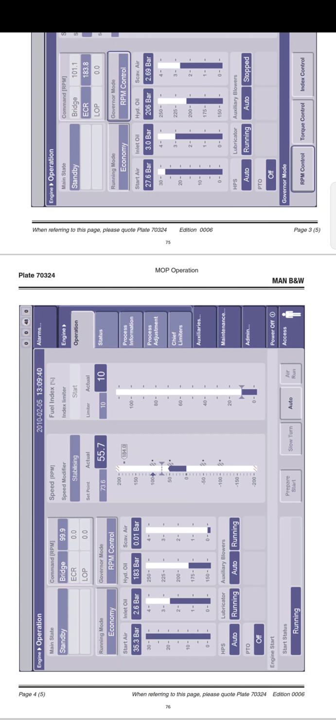Now we have the fuel index indicator. The fuel index indicator consists of a bar graph and a set of status fields. The top of the status will indicate the current effective or nearest limiter. The electronic governor will limit the fuel index command according to the actual engine operating conditions. If no limiter is currently active, the nearest limiter is displayed on a light blue background. When a limiter is active, it is displayed on a dark blue background.